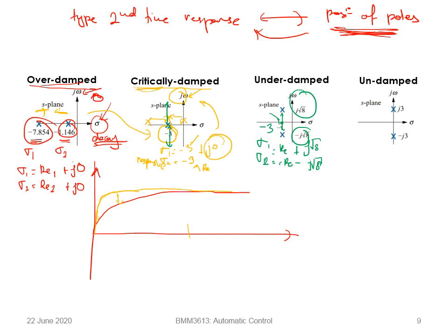So what we see now is that it has a real component and it also has a complex component. Again, what does the real component represent? The sigma part, or real component, represents the decay, whereas the j omega part represents the undulation, or sine wave, or you might call it a vibration as well. So now it has both. It has decay and it has undulation. So what is the decay? Decay is basically an envelope that represents the signals. So you will have something that looks like this now.